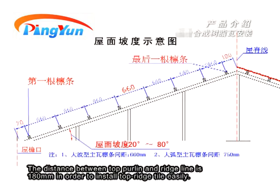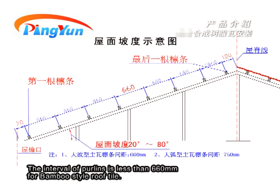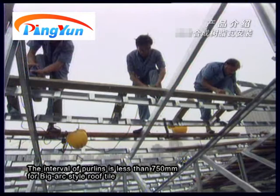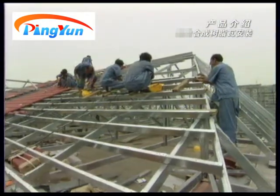The distance between the top purlin and the ridge line is 180 mm in order to install the top ridge tile easily. The distance between the bottom purlin and the eave is 50 to 70 mm in order to install eaves. The interval of purlins is less than 660 mm for bamboo style roof tile, and less than 750 mm for big arc style roof tile.